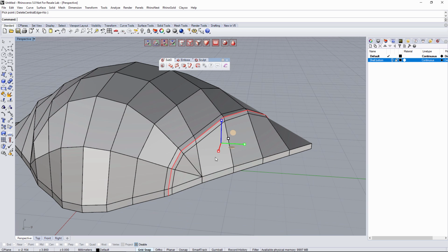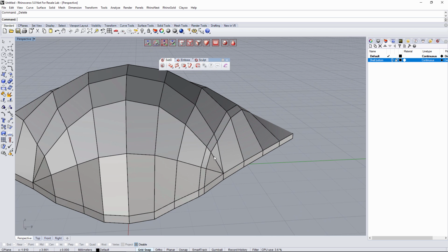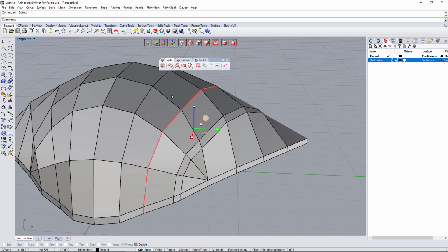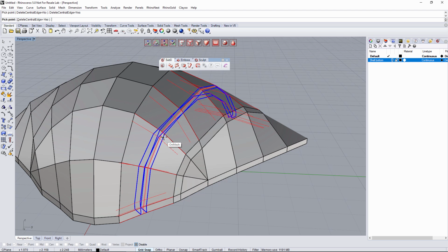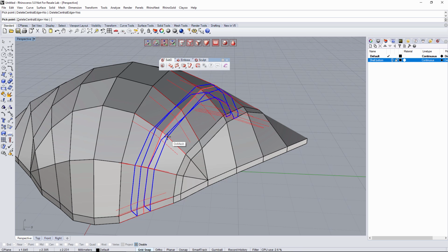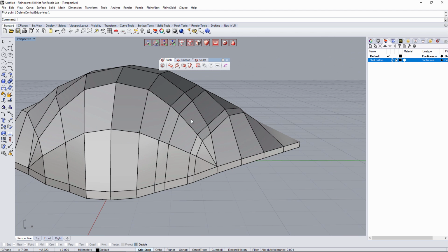And for sure I can double click on the edge of the center and delete it. For sure, in here I'm gonna show you another way. So if I go in here and go for the split side, I have the option to delete central edge. I'm gonna say yes in this case, and when I create this new geometry, something like this, it automatically deletes the central edge, so I don't have to create it manually.